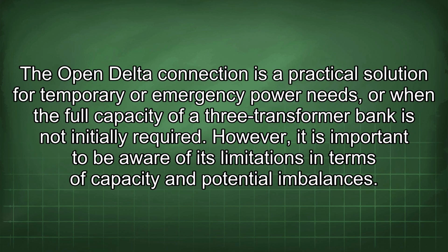The open delta connection is a practical solution for temporary or emergency power needs, or when the full capacity of a 3-transformer bank is not initially required. However, it is important to be aware of its limitations in terms of capacity and potential imbalances.